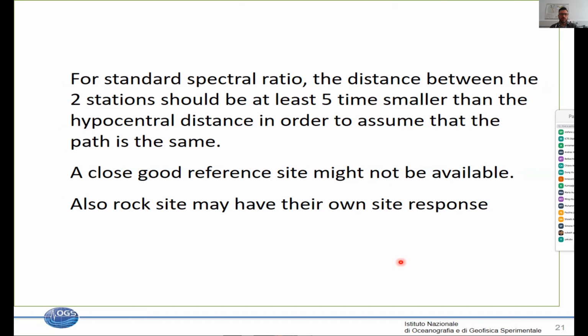So this would be preferable. Yeah, I was actually using Konno-Ohmachi. Okay, yeah, I was curious, thanks. In this case, I use a factor of 20, which is a compromise between large smoothing and avoiding too many large jumps in the spectrum.